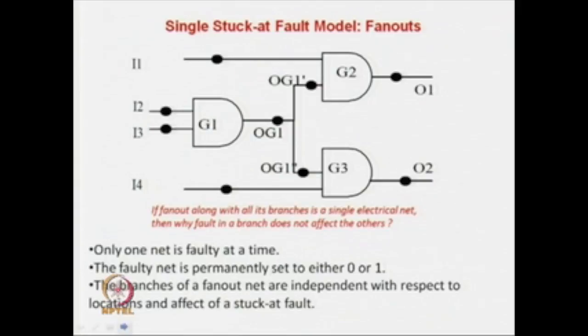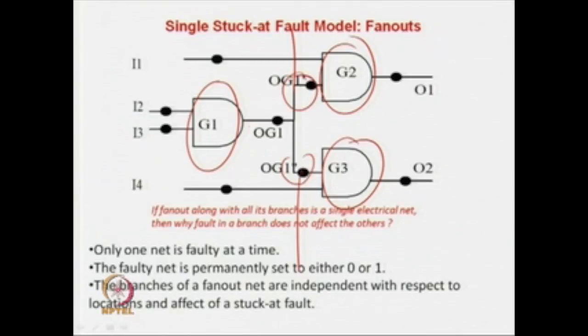So, let us see how a circuit with a fault model will look. So, this is a circuit. Now, in structural testing, we have to test this guy individually, this guy individually and this guy individually. For that we have to observe this at the output, so you have to bring them to the output. Then we have to control these two guys to test these two things. Then you have to put a 2:1 multiplexer here, and then you have to either bring this controlling line out, or you have to have a 2-bit register here to control these things. So, that was the main difficulty in this case. We reduced the pinouts by the registers, but the problem with the registers was still remaining.